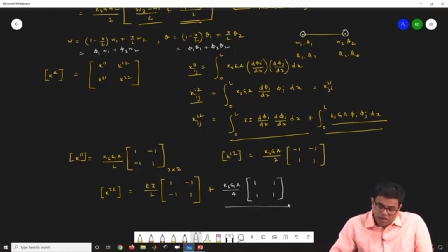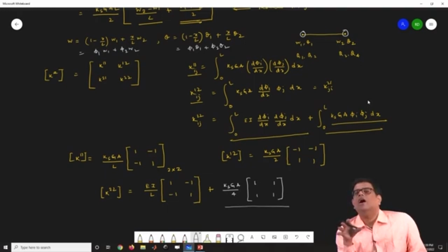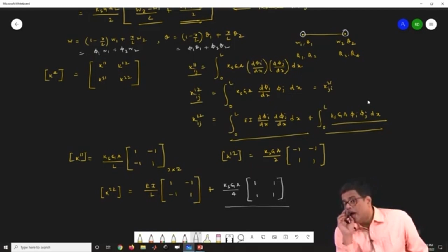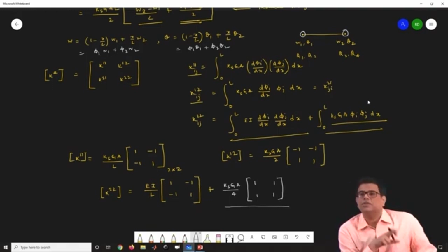Because the linear variation of phi is suppressed by the one-order-less quadrature rule, the strain energy corresponding to shear force is reduced, and this is consistent with the theory.